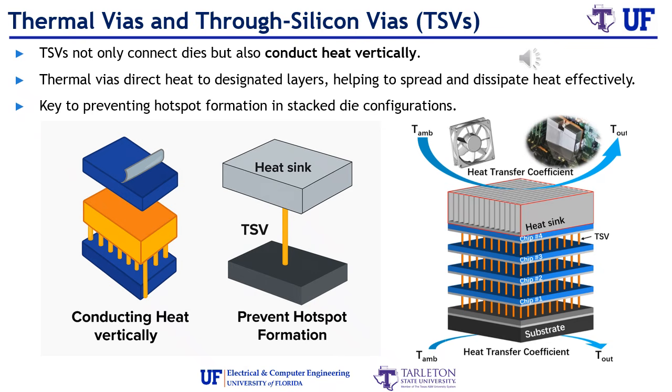Modern fabrication enables vias filled with high conductivity materials such as copper, copper-diamond composites, or carbon based structures. These allow thinner stacks and higher power operation while respecting temperature limits. As power densities rise, co-optimizing TSVs for both electrical and thermal roles will remain central to advanced packaging design.